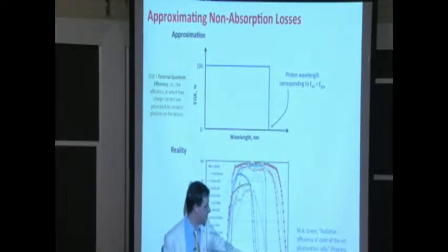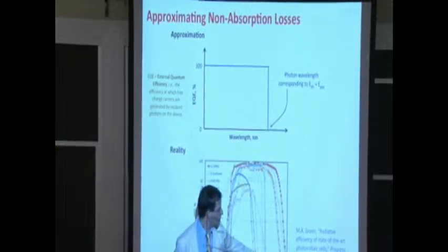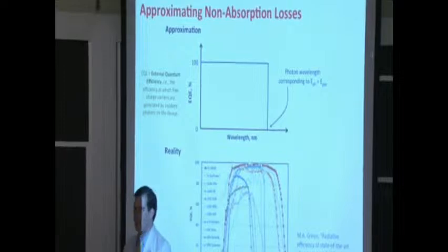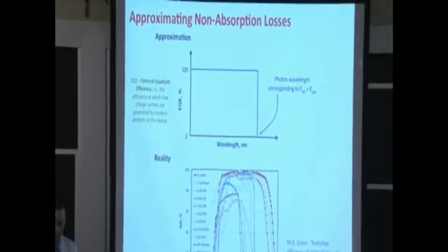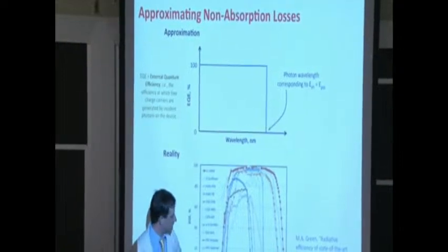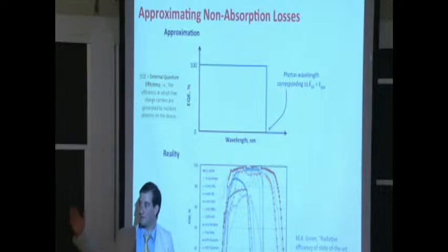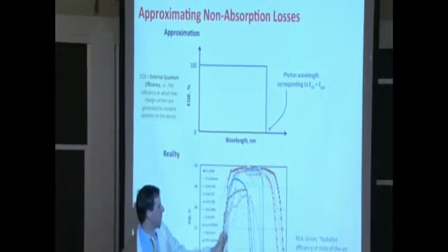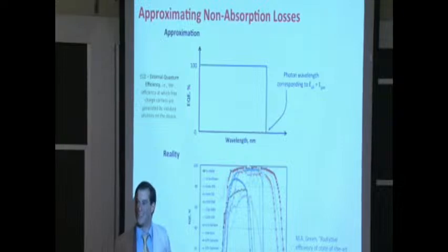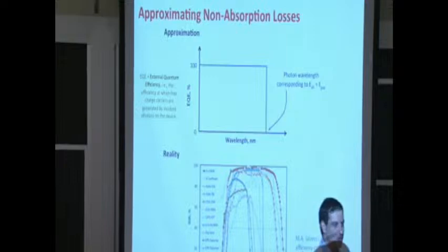So we have wavelength, different energies. Some turn on at lower energies, others at higher energies. This represents, more or less, the bandgap turn-on energy. It also has to do with the thickness, how well it absorbs light. At the shorter wavelength, though, instead of just having a QE of 1 going all the way out to X-ray territory, we have a turn-off at some point. Why is that? Why in a real device would we see that?